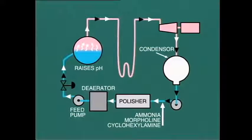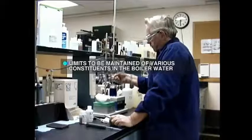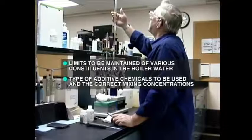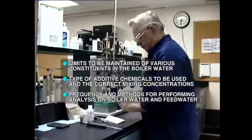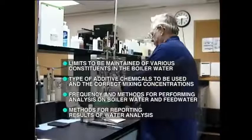and the boiler. Clearly, from our discussion here, we can see that boiler water conditioning is often a compromise, and it does require experienced water treatment specialists to establish the procedures for your particular boiler. Now, this will include the limits to be maintained of various constituents in boiler water, the type of additive chemicals to be used, and the correct mixing concentrations, the frequency and methods for performing analysis on boiler water and feed water, and the methods for reporting results of water analysis.